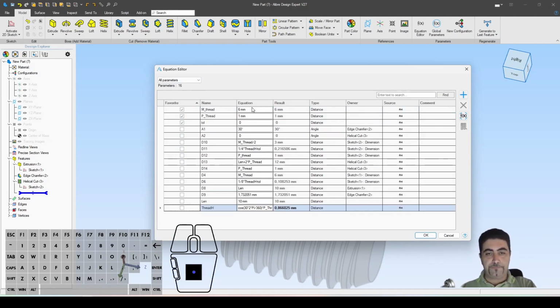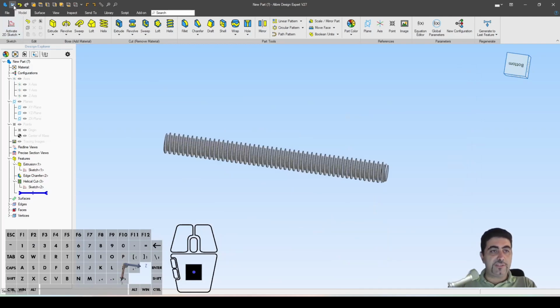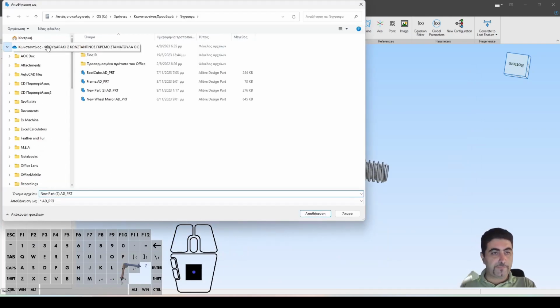Okay, so make sure that when you save this, it already has the smallest nominal diameter that you want to be using. So I'll start with a 1 millimeter nominal diameter and a pitch of 0.2 millimeters. And a tolerance of 0 is fine for now. So let's hit OK.